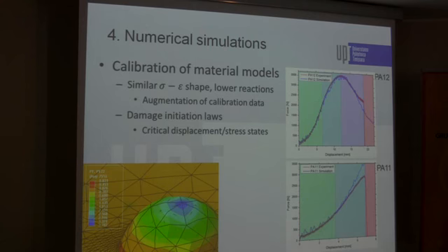and at that point in the simulation, we detected the parameters needed for describing the damage definition criteria, which are the plastic strain rate, which is seen here, the plastic normal component, the maximum shear strain, and the stress triaxiality and shear stress ratio, which are field output parameters that Abaqus can provide us with.